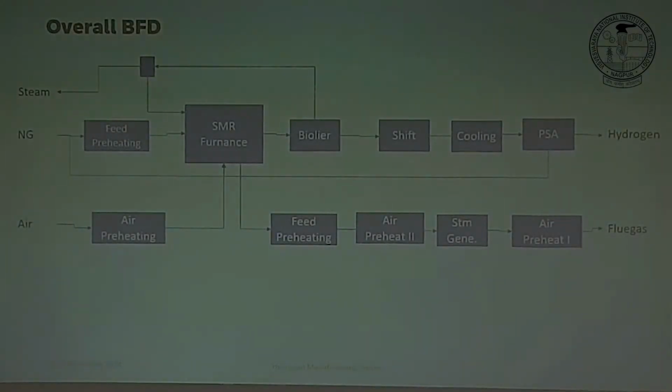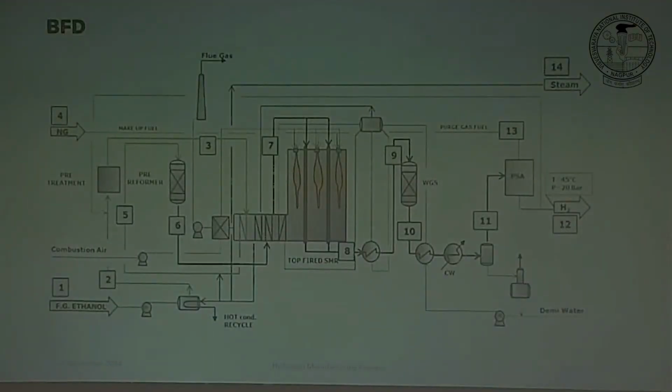So we had the R, reactive system here, H, heat integration here, separation here, and final cooling from 150 to 30 degrees, that's utility U here. So that's how we complete our onion model for the process design. And that's how the overall block flow diagram looks.